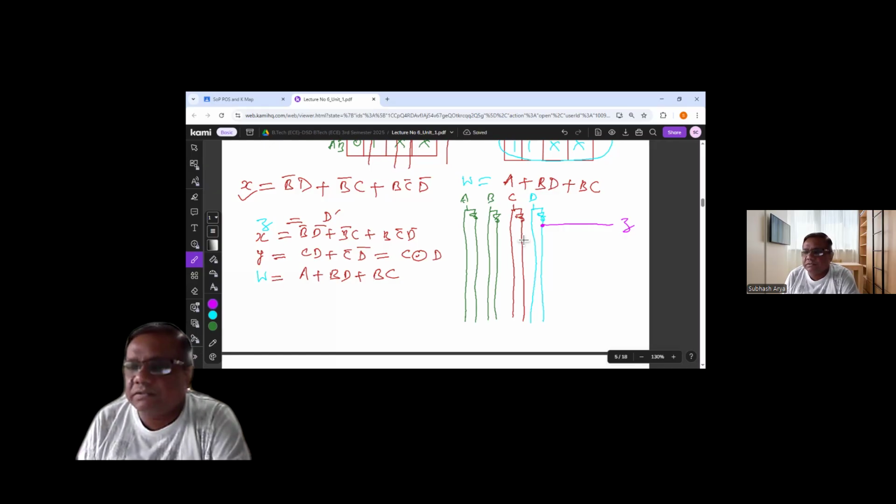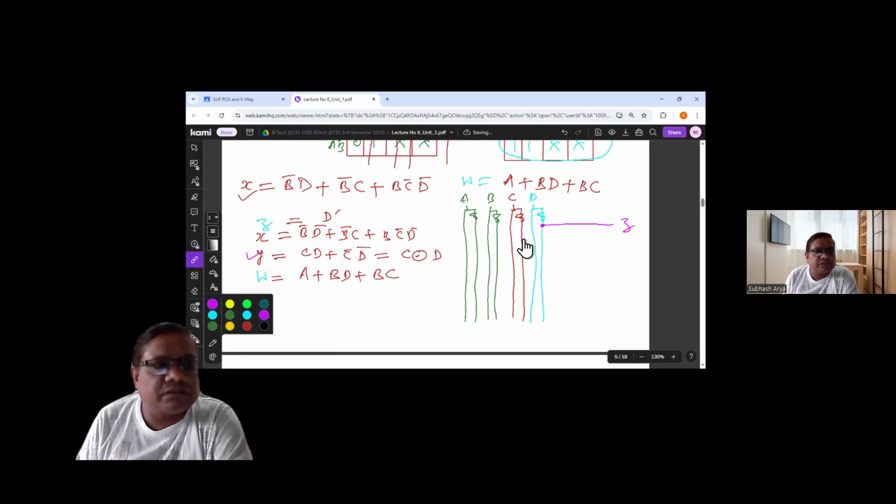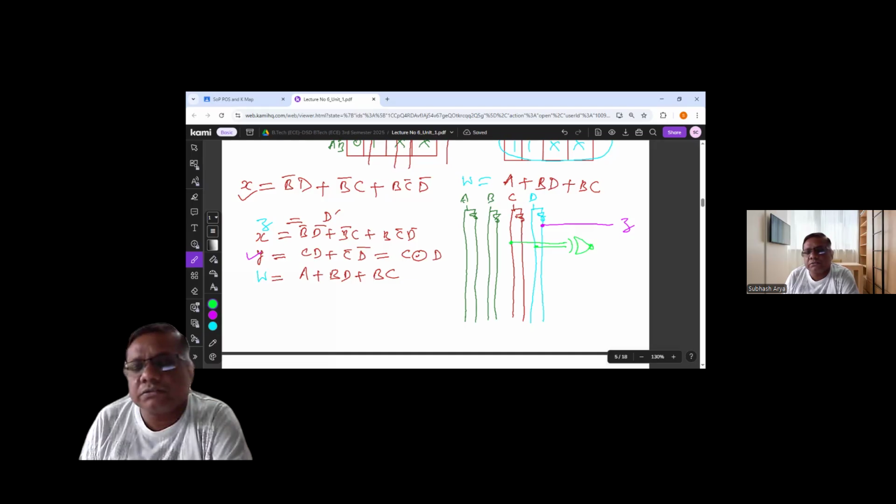Then the next one is Y. So Y I will implement as C and D exclusive NOR. So C is here and D is here, and I will take an exclusive NOR gate. This will give you Y.